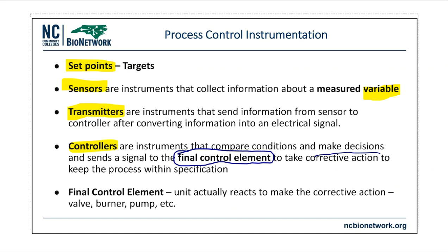So then that controller is going to send a signal. It's going to send an order. It's going to send a command to what we call the final control element. The final control element that you see on the bottom of the screen is actually what is doing the work. It is receiving that order from the controller, and that final control element says, oh, okay, you want me to increase the pH? Okay, not a problem. I will open up this valve and we will flood in whatever solution is going to be used to do that, and then we'll close that off when you tell me to close it off.